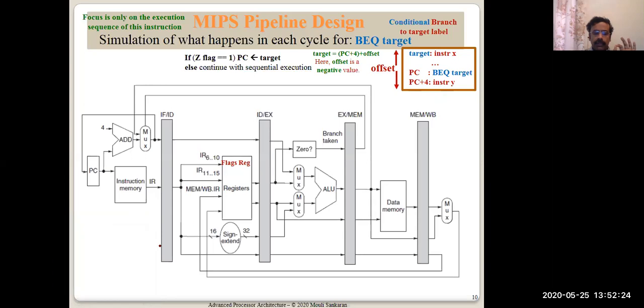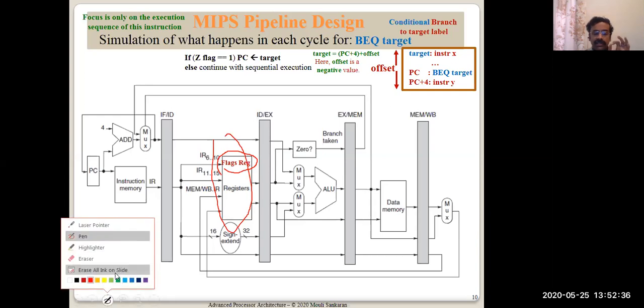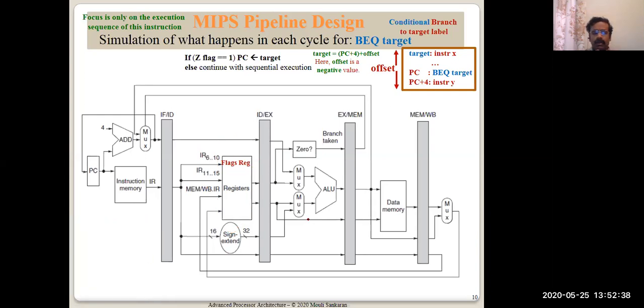Now I am explaining that the flags are a set of bits grouped together and put in a flags register, which is also maintained as part of the registers so that instructions can access or use it. But the problem here is that flags are impacted by the operation done by the ALU. Flags are affected by the ALU operation. So it is maintained physically and affected by the hardware which is performing the ALU operation here.